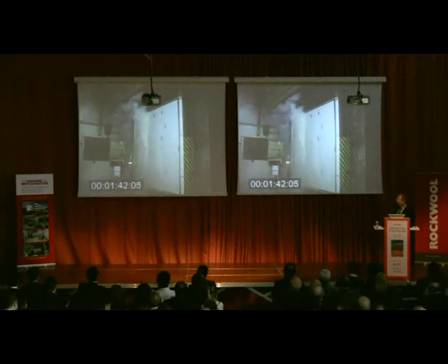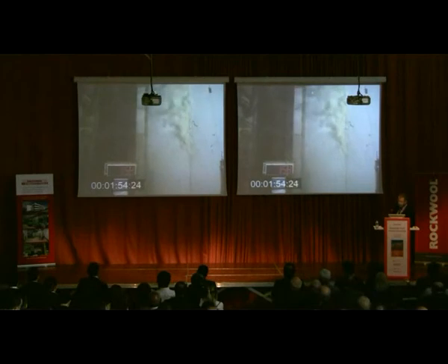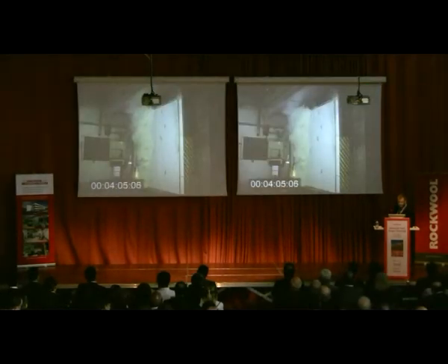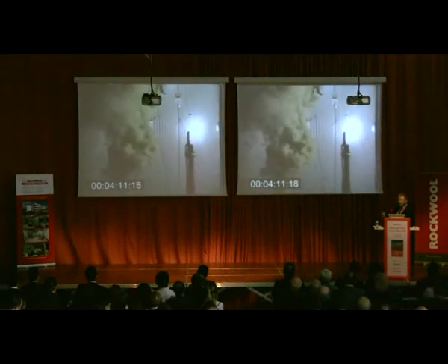So we are now on the safe side of the structure, and this is not a problem for fire resistance test. But this is quite commonly seen on fire testing like this one. We can see some small flames here, but this was not considered a failure because it was not through the panel or through the joint.